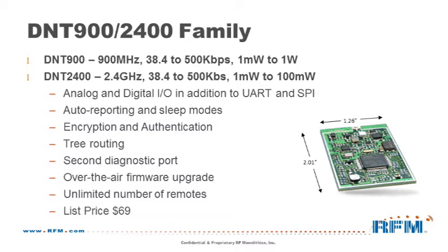Now this is a nice feature to have because you have an application that doesn't have to sit there and poll all of the nodes. The nodes are going to auto-report on whatever situation it's configured to do. So it's a very powerful feature for the radio, particularly with the analog and digital I/O. So now you have the ability to create a wireless sensor node that doesn't require any other intelligence. All the intelligence is in the radio module.